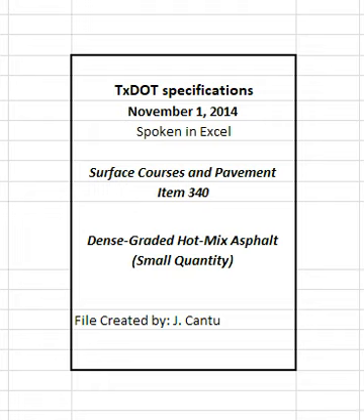Place mixtures only when weather conditions and moisture conditions of the roadway surface are suitable as determined by the engineer. The engineer may restrict the contractor from paving if the ambient temperature is likely to drop below 32 degrees Fahrenheit within 12 hr of paving.